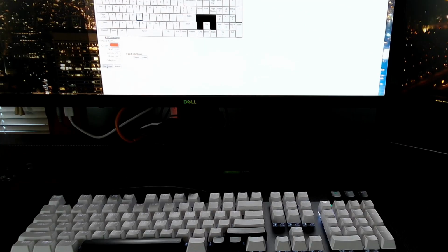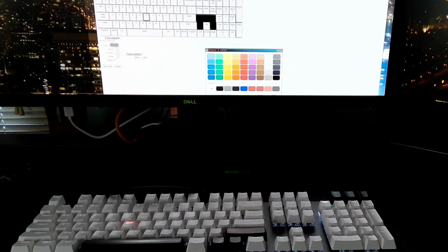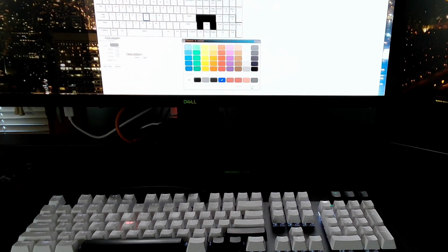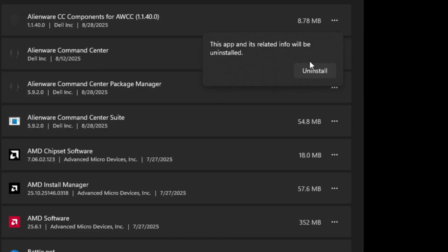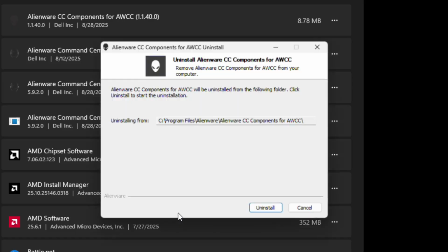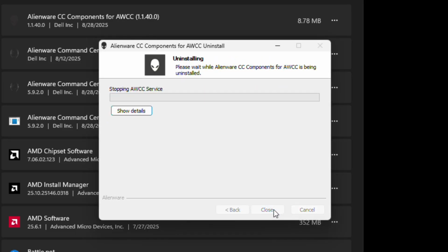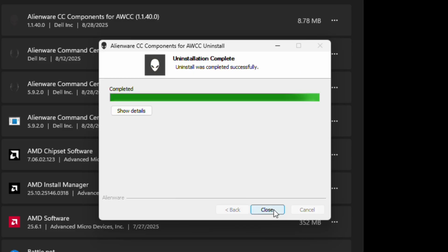With that, we're done. We have a Pico 2 set up to control the RGB settings of our keyboard, and we can configure the color for each key from a web page served over the USB connection. The advantage of this, of course, is that we don't need to install any software onto our computer to configure or change our RGB settings, and the web page to do that should work on any operating system.